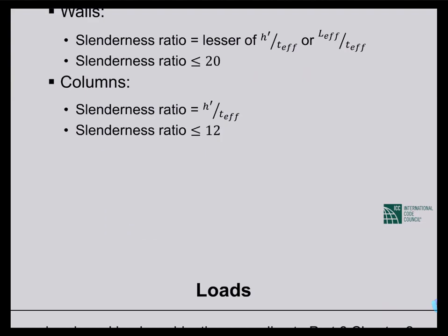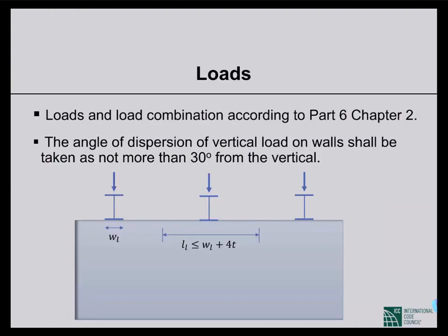We need another piece of information, and that is related to loads. Loads will follow Part 6, Chapter 2, that is dead load, live load, wind load, earthquake load, as defined in Part 6, Chapter 2. Those things were discussed previously in other sessions, so we'll just follow them, and we'll follow the load combinations of working stress design or allowable strength design.